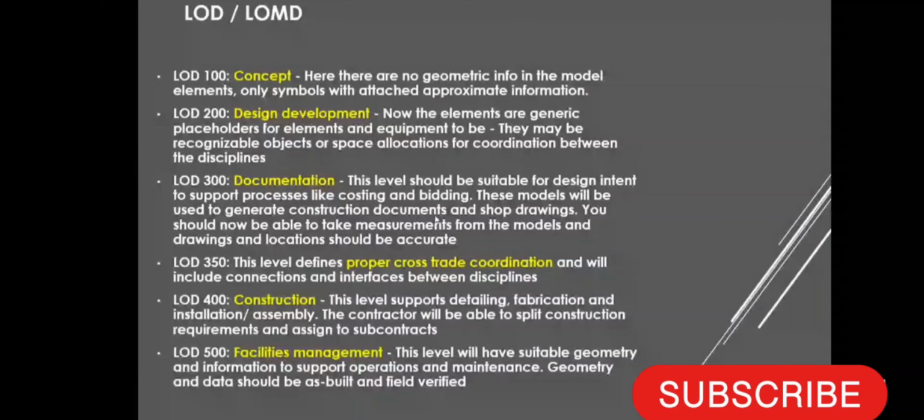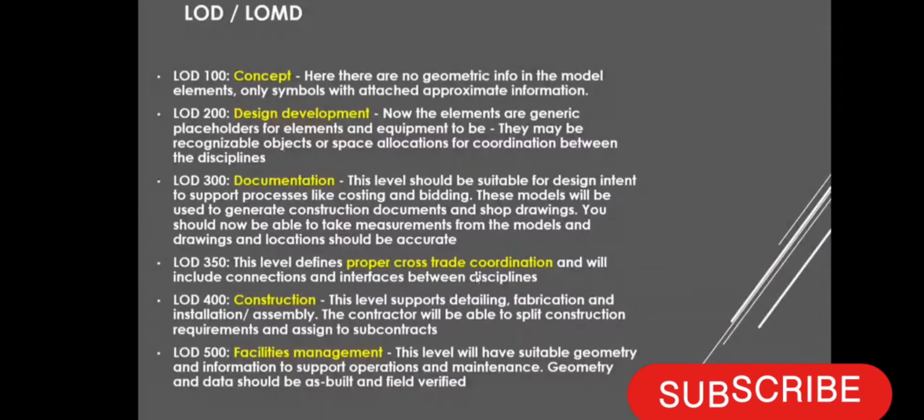In LOD 350, there will be proper cross-trade coordination between disciplines. For example, the architect is creating their model, the structural engineer is creating their model, and the MEP engineers are creating their respective models. In LOD 350, the output model will be coordinated with all other trades. If I am submitting a mechanical LOD 350 model, it means my model is coordinated with all other stakeholders. It is not creating any issues with other stakeholders.